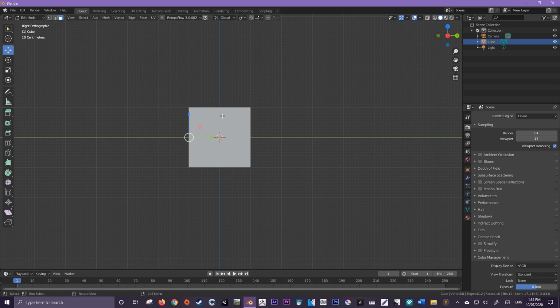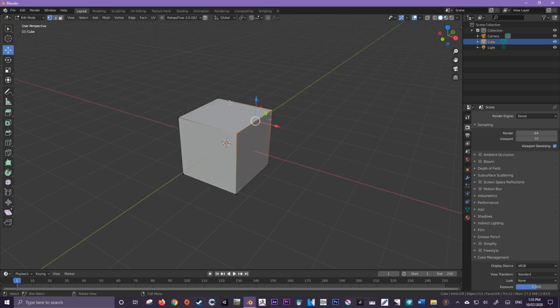And what we would like to do is turn this into sort of a rhomboid. So we need to essentially move these edges closer to the center here. To do that, what a lot of people will do is they'll select the vertex select mode, they'll drag, because I'm currently in my select box tool, and they will then try and scale it by pressing S. But as you can see, we actually haven't selected the vertices behind these. So let me just jump back to that view and let's do it again.